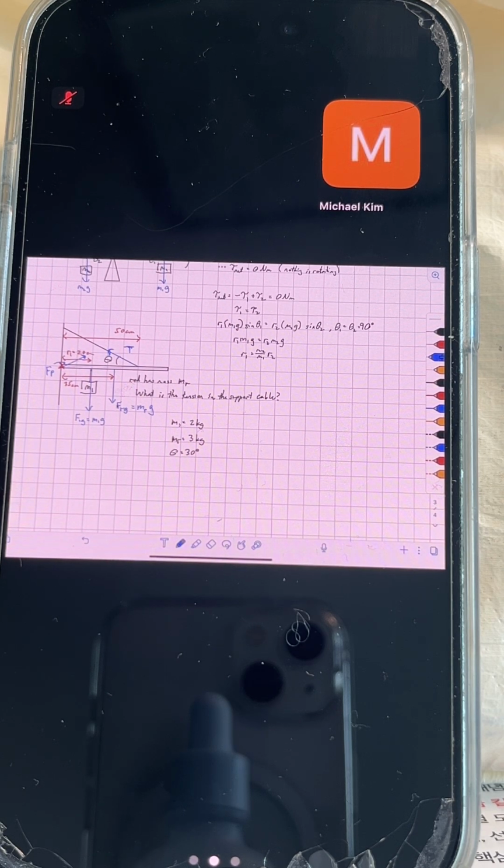So I said, is there gravity? Yes. What are we touching? Well, we're touching this block, we're touching this rope, but I forgot to include, right, we're also touching the pin here at this end, and so I've got a force from that as well. Okay. Now this one, this direction I drew, honestly, I drew kind of randomly because in this case, I don't have an easy way to tell exactly what this direction is going to be. So it could end up being that this thing is actually pointing down. We'll kind of see what happens when we work this out. Okay.